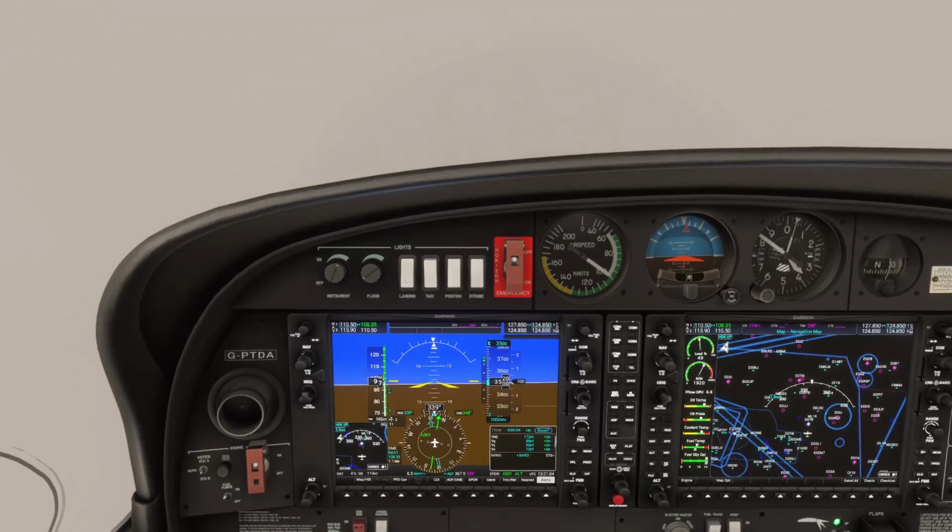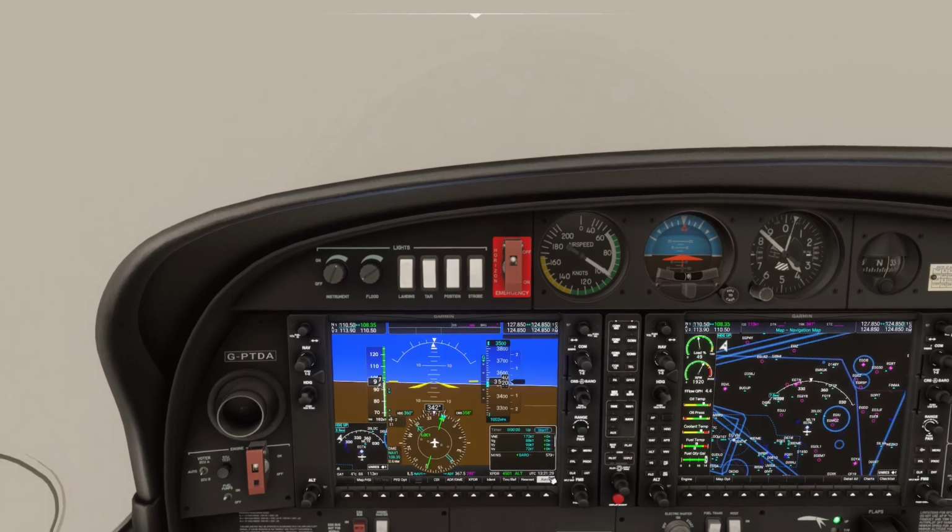So we want to twist the course to set the outbound course, which is 358, and we're preparing for the event to turn. So we're coming about 0.7 now, so you can see the needle starts to flip. I'm just holding my heading as we're in the cone of confusion. So I'm twisting my heading to the outbound heading, still holding this heading and waiting for the needle to flip.